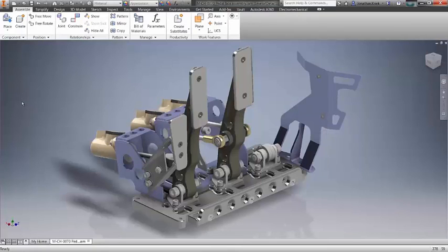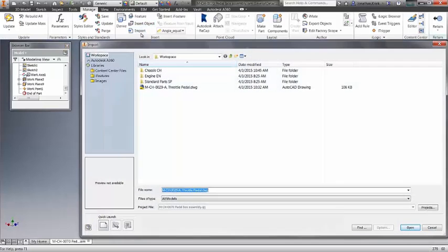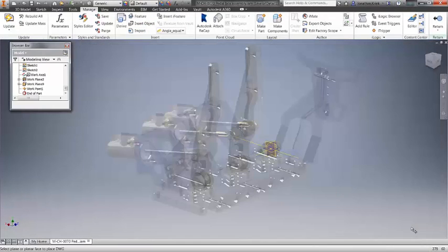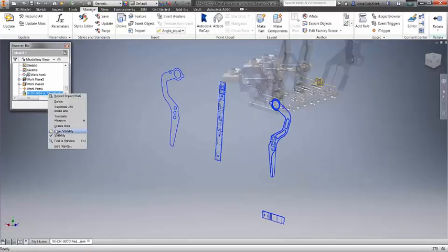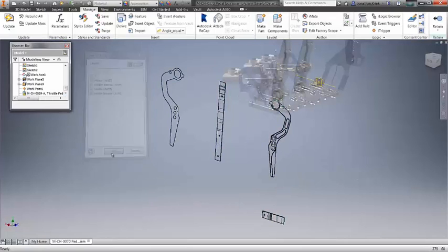Once the 2D drawing is imported, you can control layer visibility to access just the geometry you need. And you can translate the underlay to line up origins between the drawing and your 3D model.